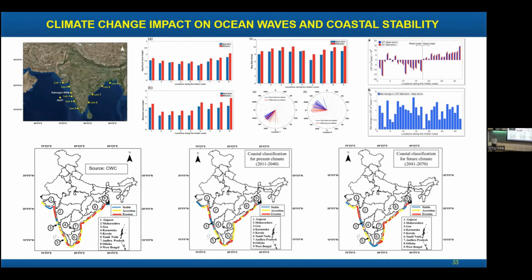How do we find it? We take a wave record. So I will have values H1 to Hn, n number of wave heights. What I do is take the average of the highest 1/3 of the wave heights.